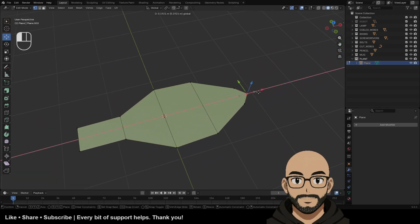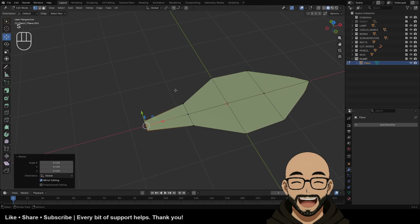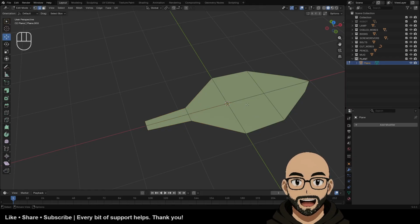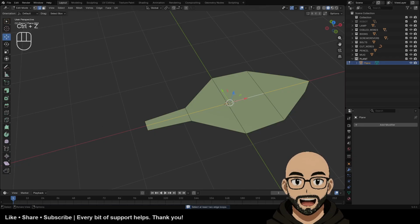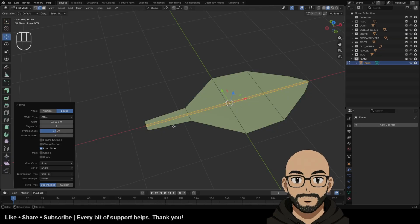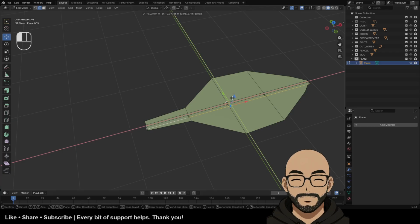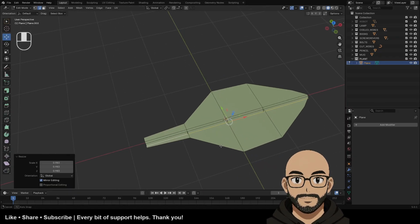And now I'm going to move this point forward like this. So we want that nice point. And then this is going to be nice and narrow. Then what I want to do is bevel this edge and push it down. So select this entire edge loop. Bevel edge loop. Oh, not bridge, so bevel edge loop. There we go. And now we've got that little split. Increase this to 3. Select this middle one. Push this down and scale it in a little maybe. Well, we can play around with that.